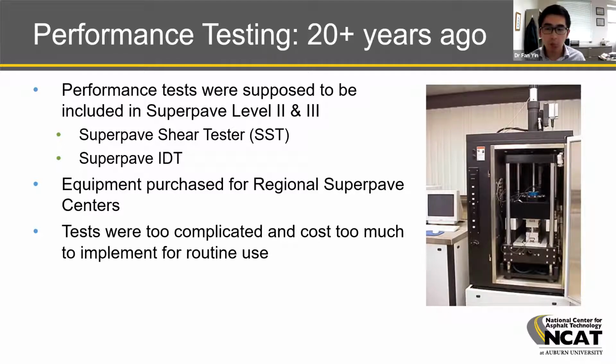There was some equipment purchasing for regional Superpave centers here in the US. But the reality is the tests were too complicated, in terms of the way the test was run or the data analysis that was conducted. So it was not widely used. There were only a few special projects where we applied the test during mix design and during production. Other than that, it was just a piece of equipment sitting in the lab and nobody really used it.